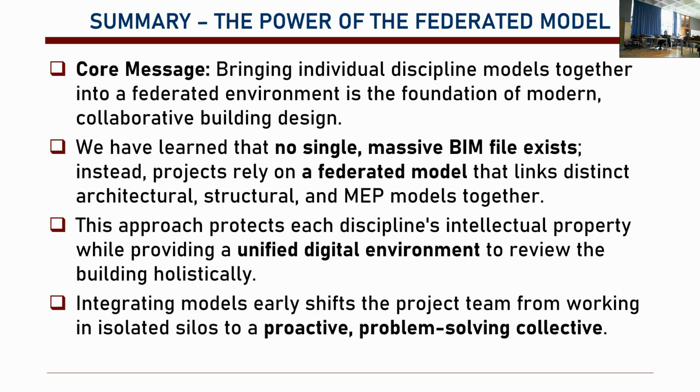Well, federated model. We bring together different disciplines and we make them work together. We know that we cannot have a single massive BIM file. A federated model basically links architectural, structural, and MEP models together. So we have distinct models, but we bring them together in a federated model. Here we give a unified digital environment for all these people to work together and find what's going on. And we are doing that to reach proactive collective problem-solving.